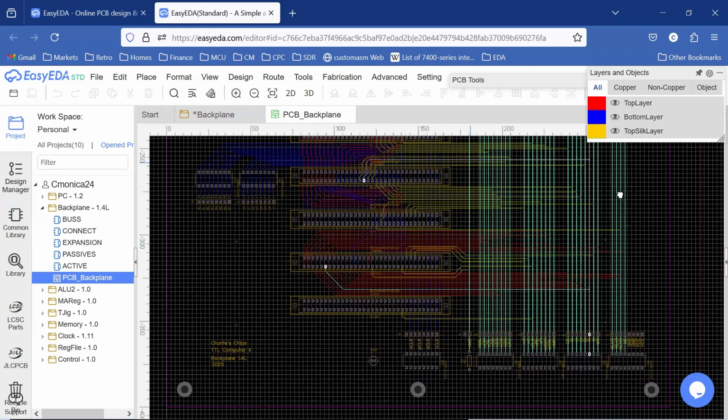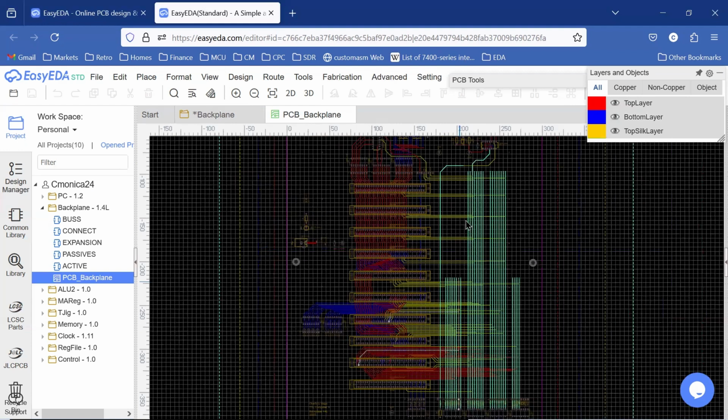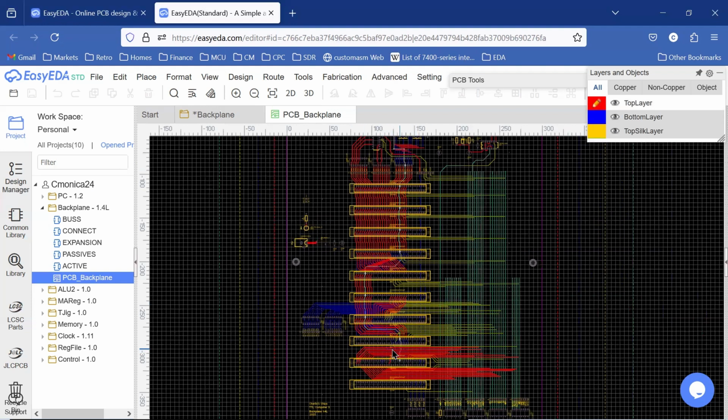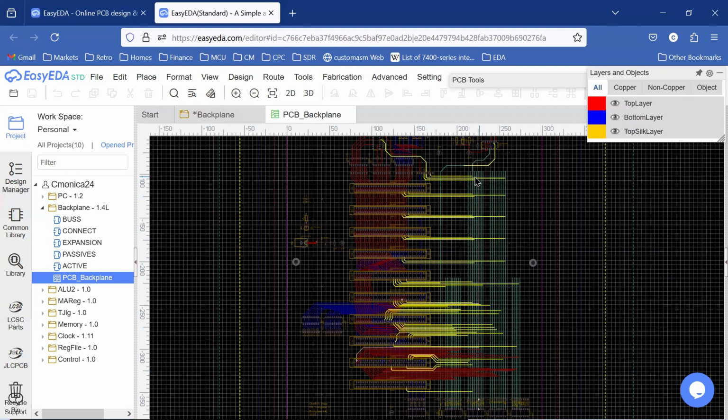These are our control signal bus lines, right? And they're running the whole right side of the PC board. So those are there on the board. And again, you can see here the control lines coming out from the controller, being brought out to the control bus lines. And then we have the yellow, which are the control lines coming in from the control bus to each of the cards as those signals are utilized.